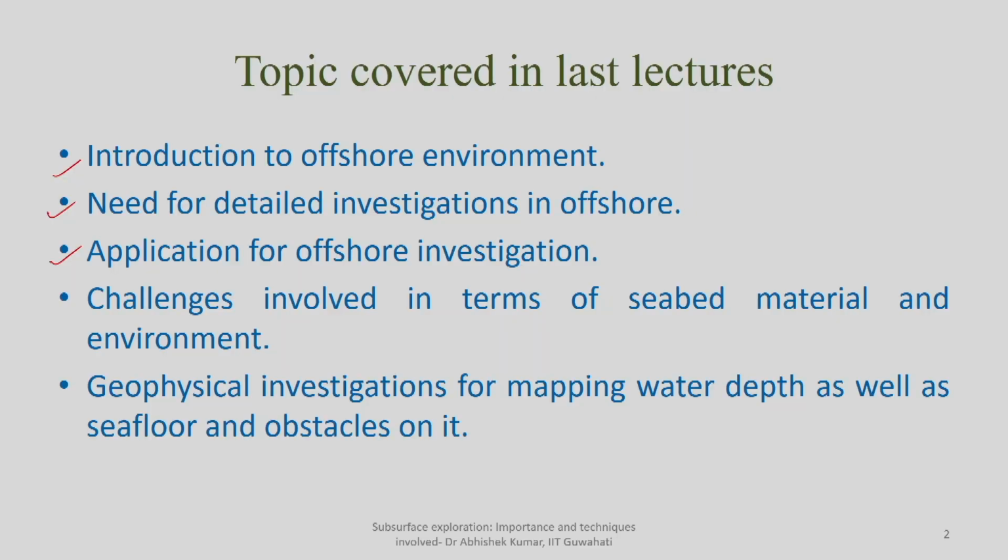Then owing to water waves and water currents at shallower as well as deeper depths, and the suspended load in sea water, sand dune deposition, weathering, erosion and so on are governed. Depending upon the height of the sand dunes, sometimes they can provide immense pressure on the foundation of any existing offshore structure, which can lead to failure of the foundation, bearing capacity failure, or settlement failure as well.